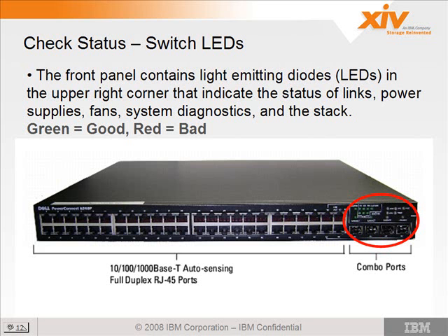So during our maintenance lab today, what you're going to do is pull the AC power from a switch and take a look at the LEDs, and plug the AC power back in and pull the RPS cable and see what that light looks like. Let me give you a word of caution. If you pull the RPS power, there's a little tab on the top of the connector. You want to push the tab down before you pull the connector out. Anthony learned that, right? That's right. So yeah, make sure you plug it back in.